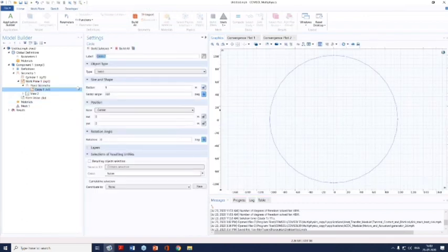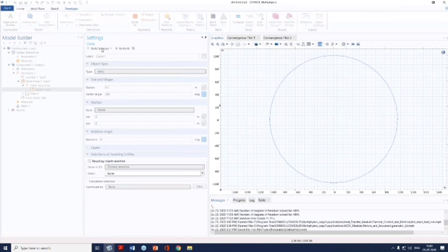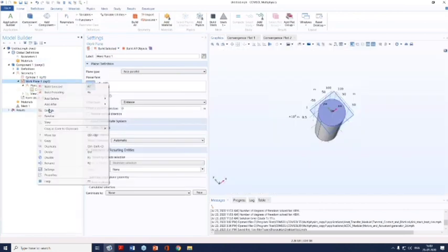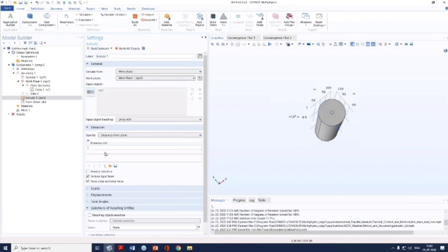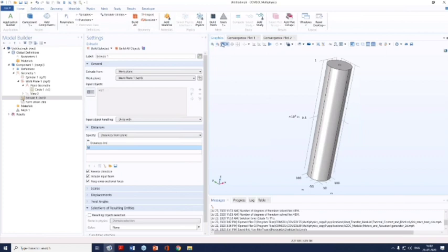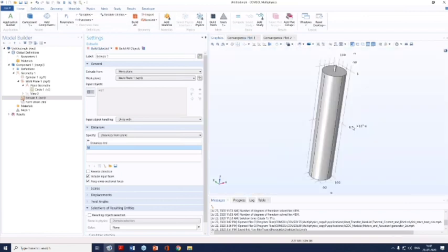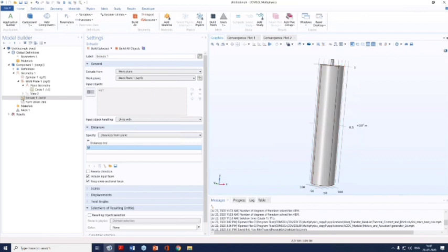So here in this case, I can just create another circle, let's say 0.1 radius. That is very small maybe. And once that is done, I can just extrude it also, let's say in the reverse direction, and I can just say 50, which is still very small compared to the 1000 meter height that we are having in this direction, as you can see. So this is how you can create it.